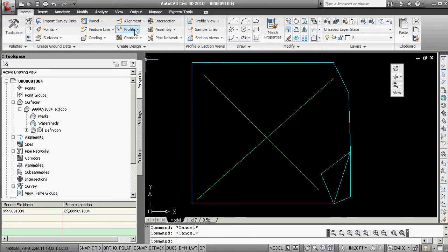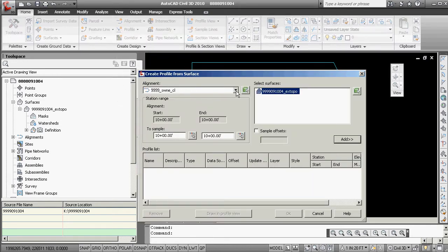Next step is to create a profile, create a surface profile. Make sure that you know which one you're doing. Obviously, I've got a couple here. It's not always the best to keep going when you don't know which is which. So I see here, we've got a southwest, we've got a southwest. That one should be the one we want to delete.